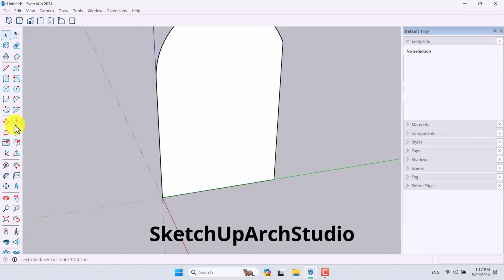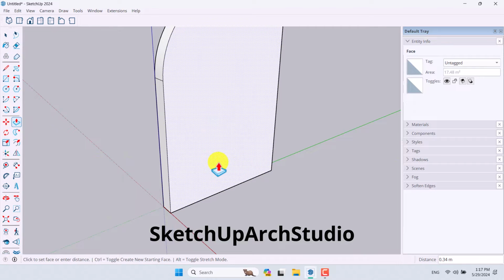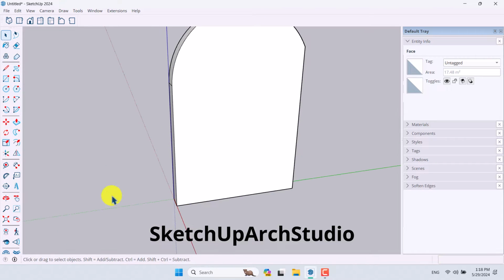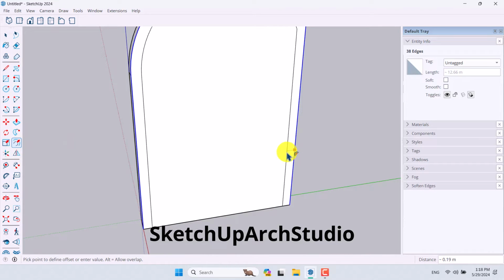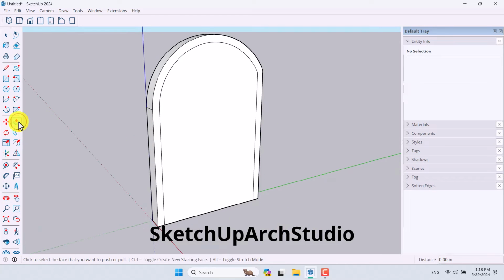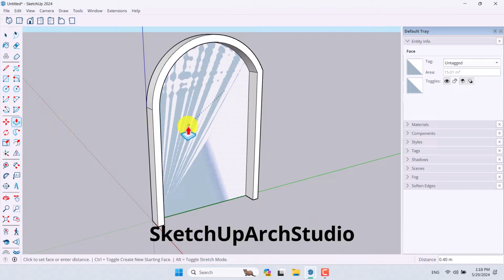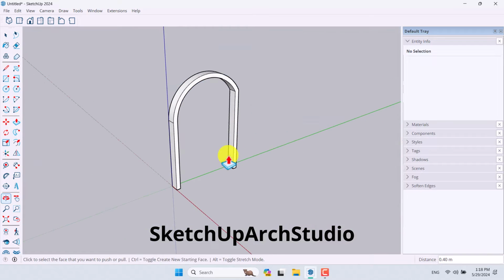You can extrude it like that, some number about, for example, 0.4. Select this face, hold shift, deselect this face and this line in here. Click on the offset tool in here. Draw your offset something like that, a little bit with the width. 0.2 is enough. All right, you can work with completely free numbers, make it per boolean like that.